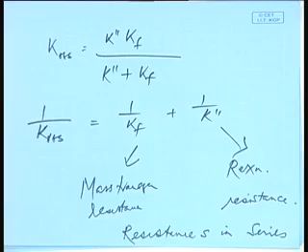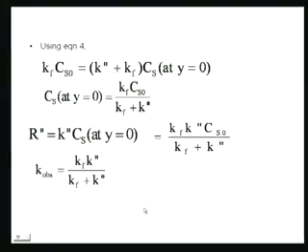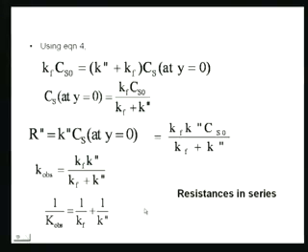So you again figure out that resistances are in series. So whether it's diffusion or convection doesn't matter, as long as the processes are in series, you can always add up resistances. Okay. So just a quick time scale analysis we'll do. These are things that we already did, so no point going through them again. So this is what we find, that 1 over k observed is 1 over kf plus 1 over k double prime, and therefore the total resistance is summation of the reactive resistance and the mass transfer resistance.